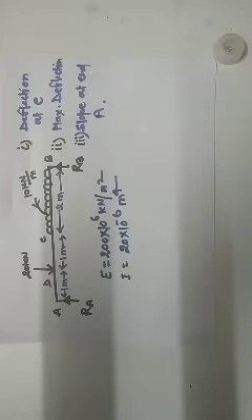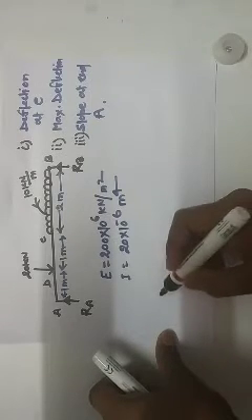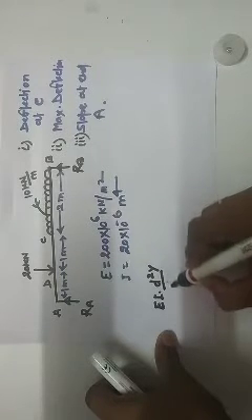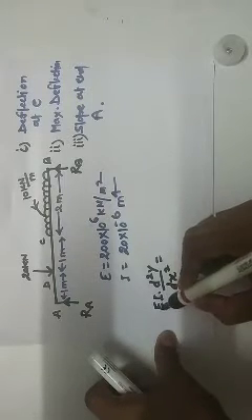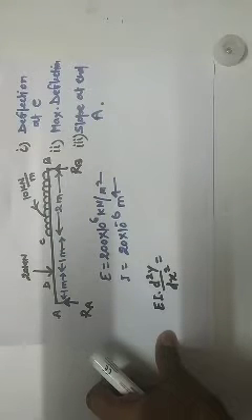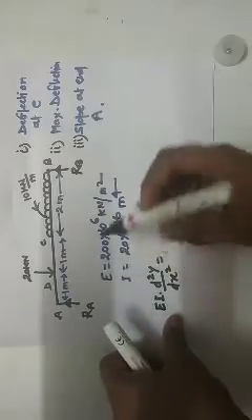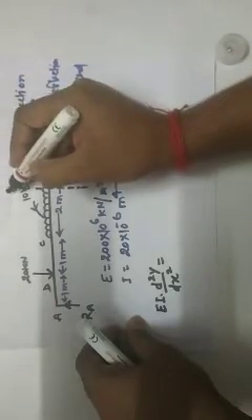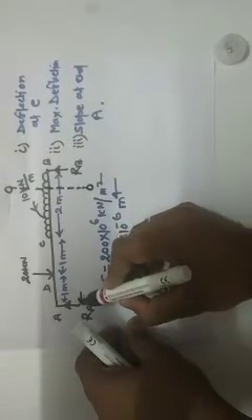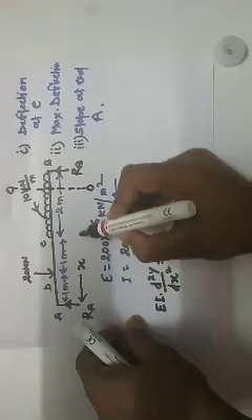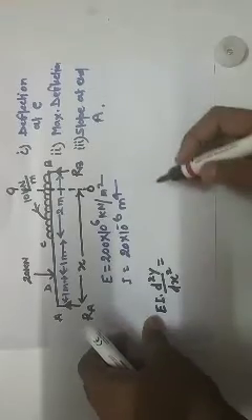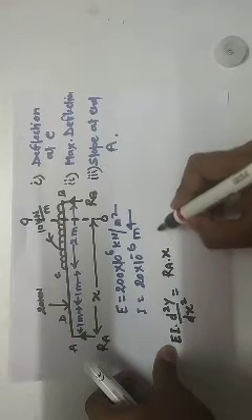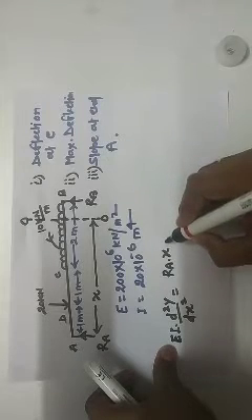Now, first we will establish a bending moment equation, EI d2y/dx2, which we call the Macaulay bending moment equation. Here it is equal to M_x. Make a section in between the segment CED, and say the distance of this section from end A is x. Then take the moment of all the loads about this section. It will be RA into x, then there will come a Macaulay bracket after the first term.